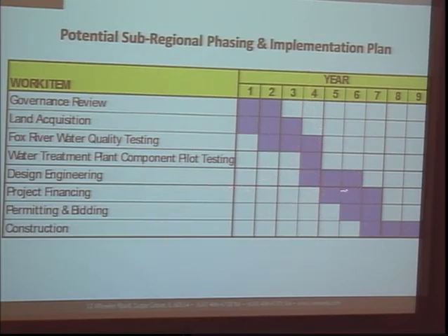So if you get down the road, and even if this delays a couple years, 5 years, whatever makes sense for you, you can reevaluate. So if population growth didn't go as was projected, instead of a 25 MGD plant, maybe you're looking at a 22. Or if somehow there was a lot of growth and it was a lot quicker in other communities, maybe it needs to be larger. But there is, again, opportunity to reevaluate.